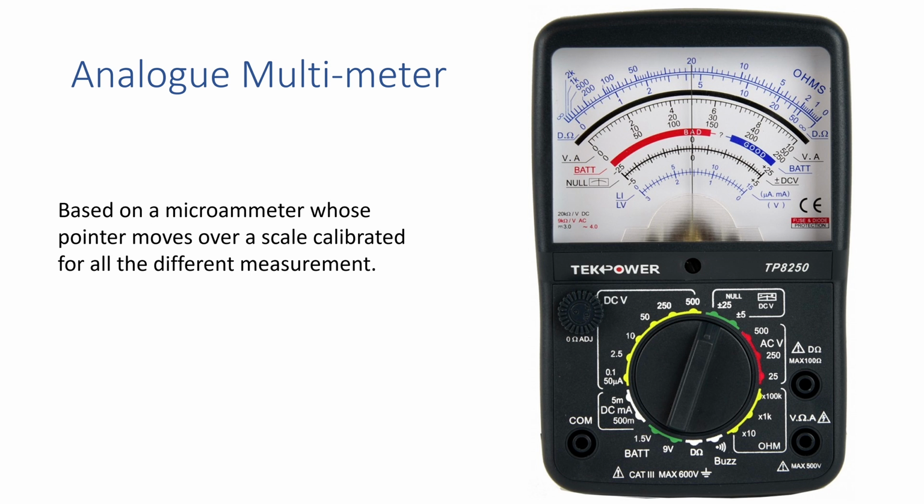So when it comes to the resistance measurement in particular, they are of low precision due to the typical resistance measurement circuit which compresses the scale heavily at the higher resistance value. Inexpensive analog meter may have only a single resistance scale, seriously restricting the range of precise measurement. Typically, an analog meter will have a panel adjustment to set the 0 ohms calibration of the meter to compensate for the varying voltage of the meter battery.